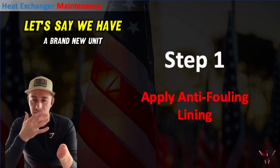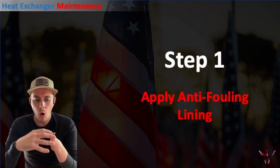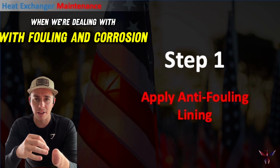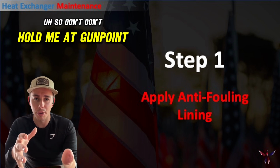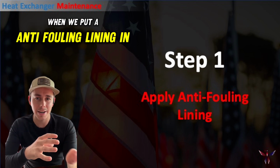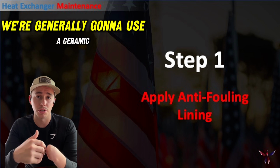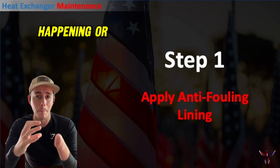Generally speaking, let's say we have a brand new unit or a unit that's just been repaired and we want to stop any issues. What I like to do first is apply an anti-fouling lining. The reason being, as a good rule of thumb, and this isn't always true, so don't hold me at gunpoint to this, when we put an anti-fouling lining in, it's naturally corrosion resistant, so we're going to already have a corrosion barrier. And what the fouling is designed to do, in our case, we're generally going to use a ceramic, a thin film system that's super smooth, is that it will stop any buildup from happening or minimize the buildup.